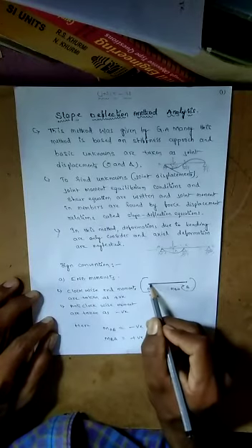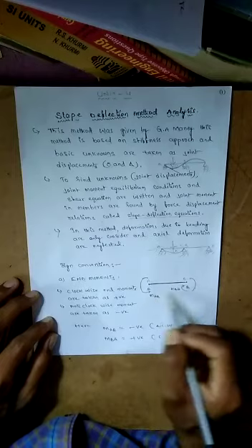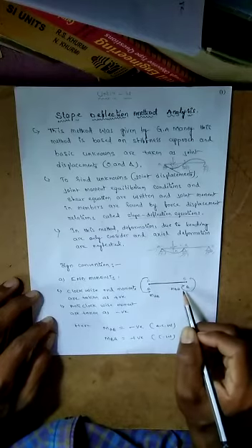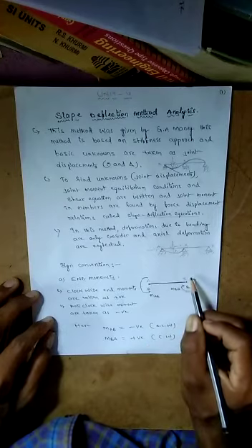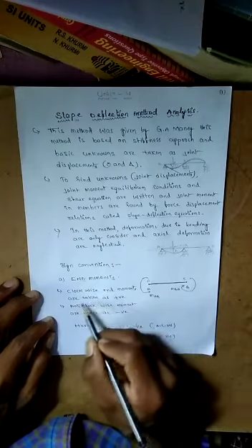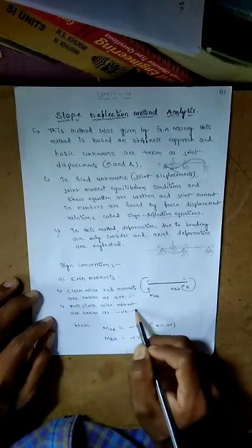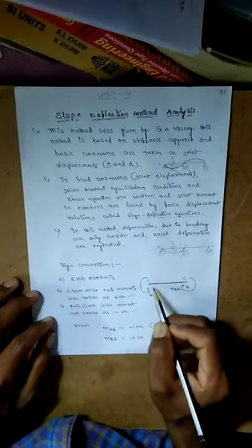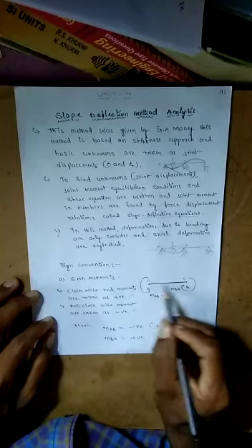This is the simple beam, the AB span. This is the fixed end moment. First, you calculate it here. This is the anti-clockwise direction, this is the clockwise direction, where the fixed end moment is developed. Here clockwise end moments are taken as positive and anti-clockwise moments are taken as negative. This is the span AB fixed end moment MAB.